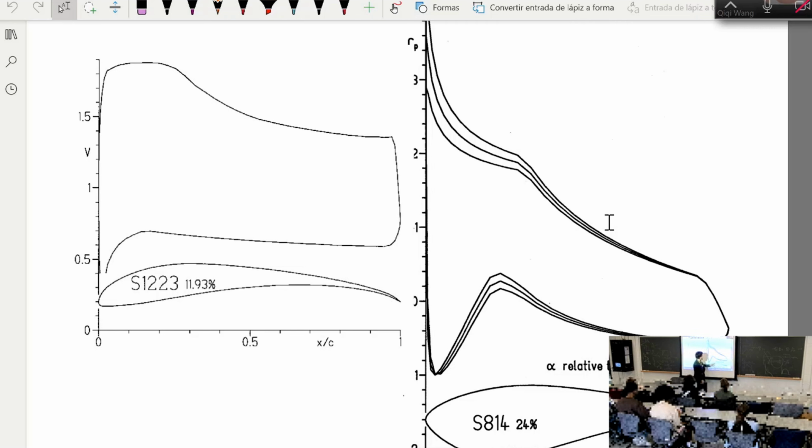So basically it is really by tuning the curve. It's hard to see here because the pressure gradient is more sensitive to curvature than slope, right? I mean, the human eye doesn't really see curvature that well. But anyway, the pressure gradient is designed to be higher over here exactly because there is confidence the boundary layer is turbulent over here. But again, a turbulent boundary layer, as it gets thicker and thicker, becomes less and less resistant to adverse pressure gradient. That's why the pressure gradient is also designed to lessen over here. So this basically underlies the design principle of airfoils that are designed to get as much lift as possible.